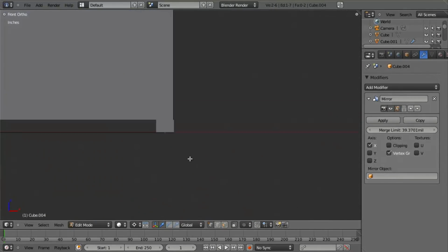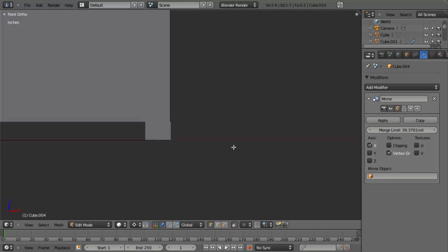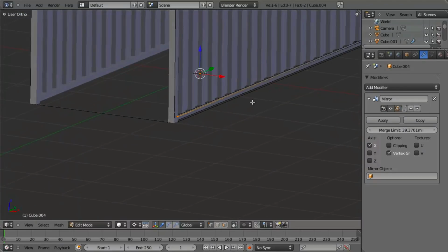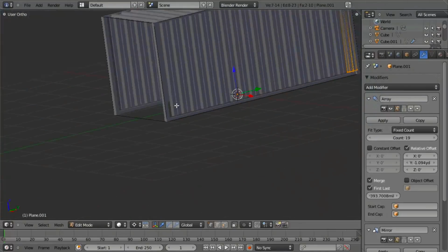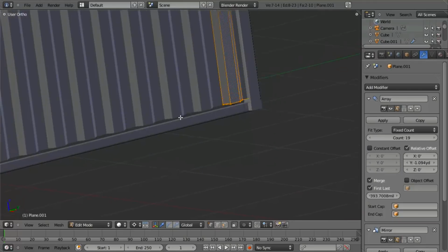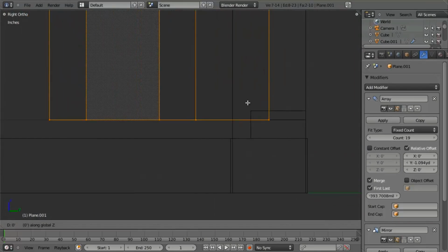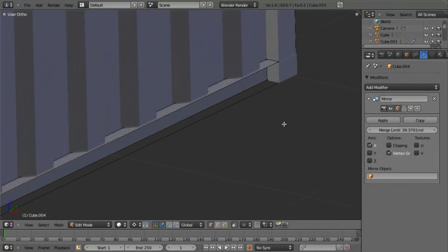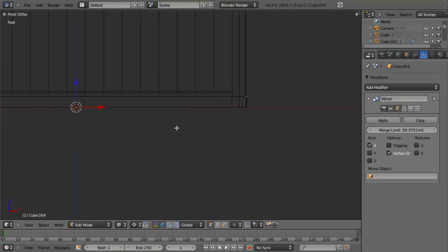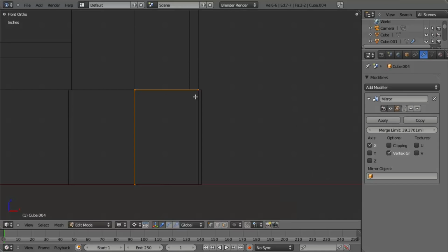And then the important thing to realize is that we're doing this all in wireframe mode. Since I have the back face culling enabled right here, I'm unable to select anything behind my current view. With that then created, just basics, let's go ahead and adjust the walls again. And so we'll just bring this right down 1 inch to right there. And then let's select this bottom piece. And then the way that we're going to thicken this is let's just add in a solidify modifier.